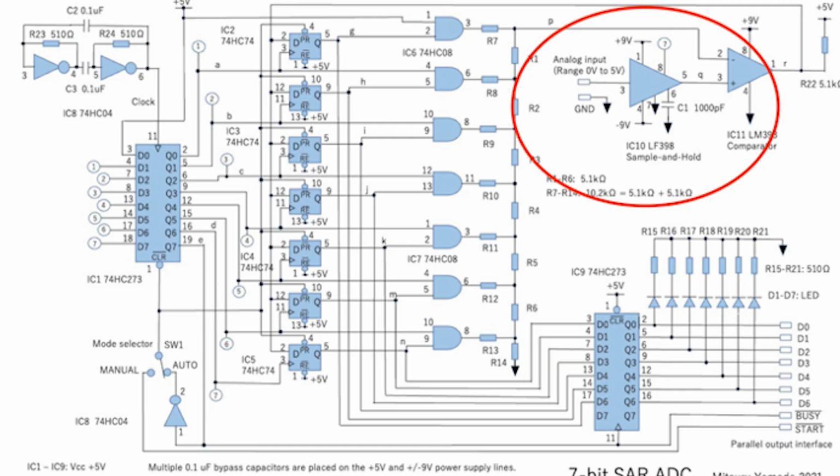The ADC is going to use the reference voltage, which in this case is going to be 5 volts, but it can handle other voltages, but that'll be displayed in other projects. So say it's a reference of 5 volts, it's going to take half of that, and then it's going to compare, using the comparator at the end of that highlighted circle, the sample voltage and reference voltage. It's going to spit out a weighting bit, either a 0 or 1, to determine whether the ADC should try a lower or higher reference voltage.